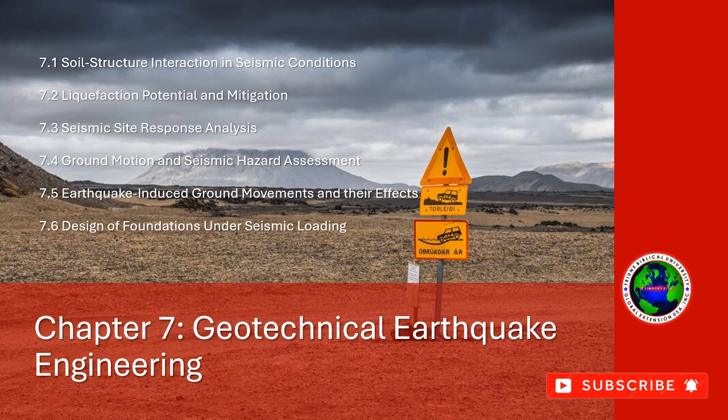Soil improvement and compaction. Densification. Increasing the density of loose soils can reduce liquefaction potential. Techniques such as vibrocompaction, dynamic compaction, and compaction grouting can be used to compact sandy soils, reducing their void ratio and improving their resistance to liquefaction.